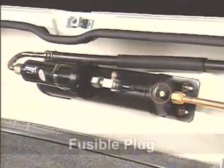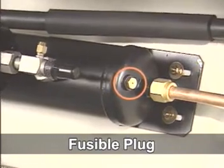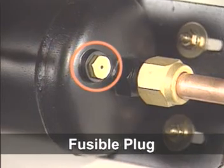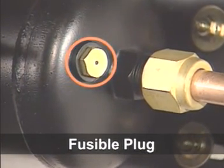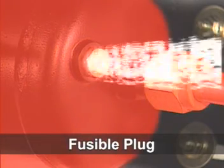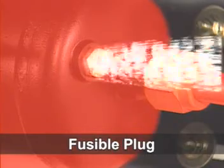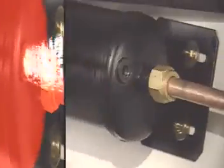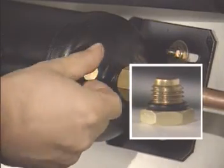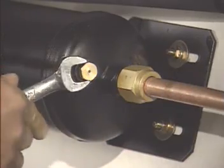A fusible plug is installed on the receiver tank. When the high pressure switch is defective and pressure increases due to an air conditioning system malfunction, there is a risk of explosion of vulnerable parts. The fusible plug melts in this case to protect the air conditioning system by discharging the refrigerant. The fusible plug is a bolt type and can be replaced by simply turning the fusible plug after removing the cause.